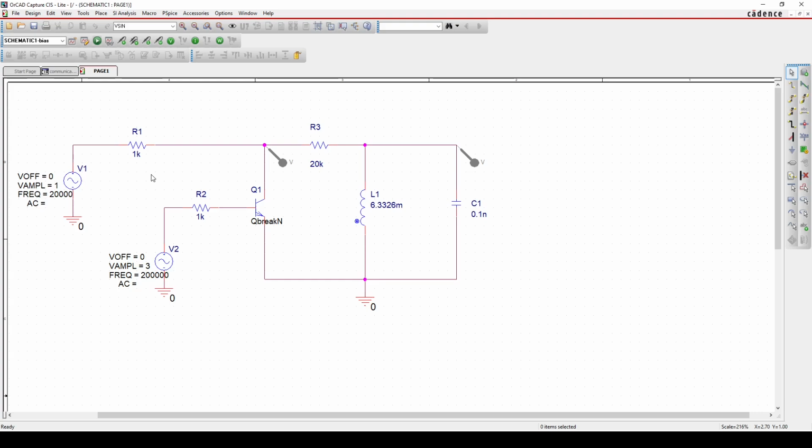And the way the circuit works is we're going to have this message signal here going to go past this resistor, and this switching source is going to go into the gate of the BJT transistor. And when this signal is high, it's going to create a virtual ground from here to this node. And when this signal is low, this message signal can pass through. So at this node, it generates what looks like a sampled sine wave that we saw earlier from multiplying a square wave and this message sine signal.